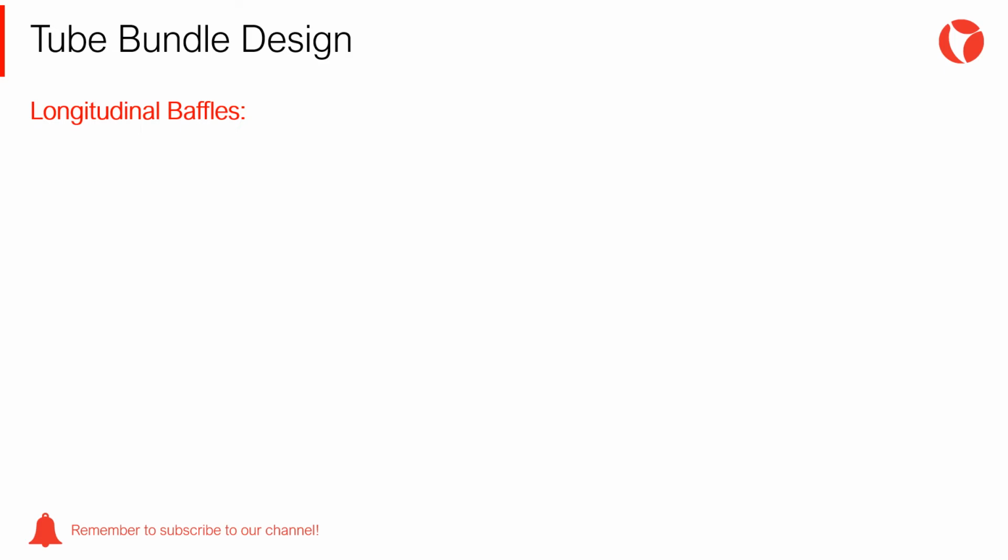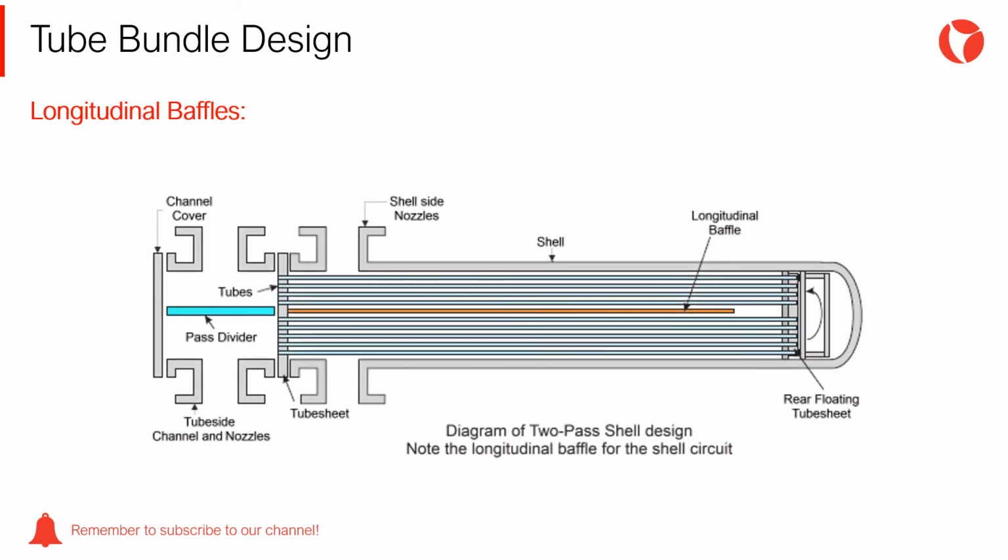In some cases, with sensible thermal gradients between the two fluids, for instance, it is required that the fluid travels the length of the shell more than once. Longitudinal baffles are used in these cases, as shown in the picture.